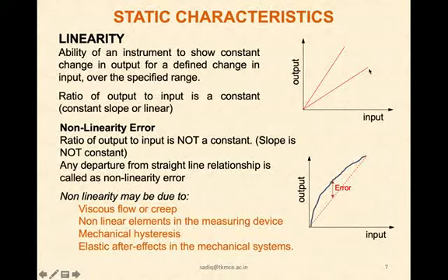If there is predictability of the output, we can predict if some error happens. In the case of a non-linear instrument, predicting errors is very difficult. Unfortunately, most instruments introduce non-linearity error, and good instrument manufacturers typically state the non-linearity error throughout the range.